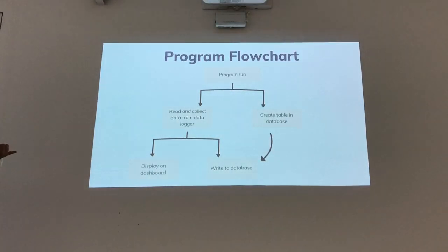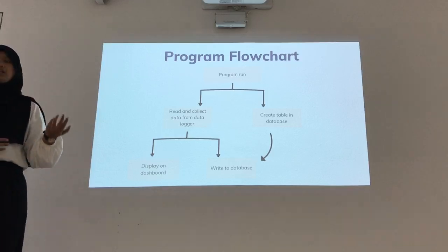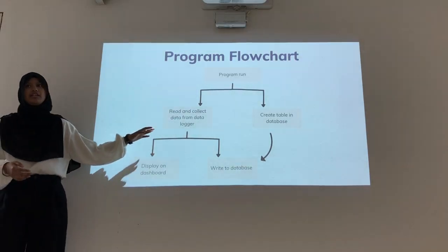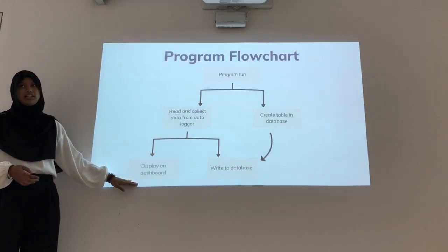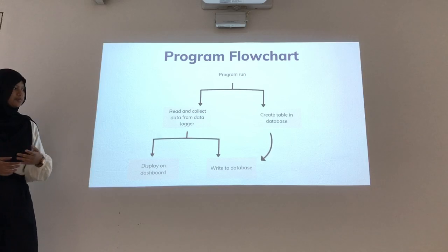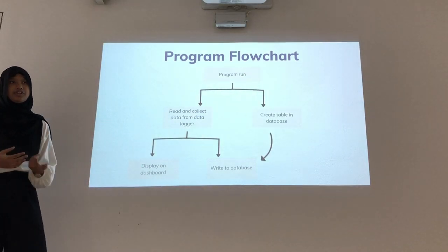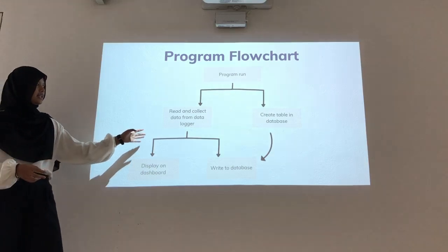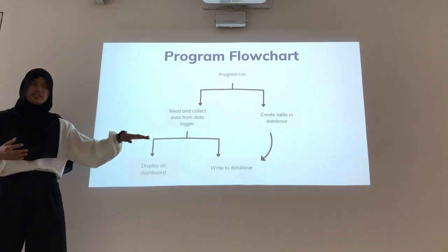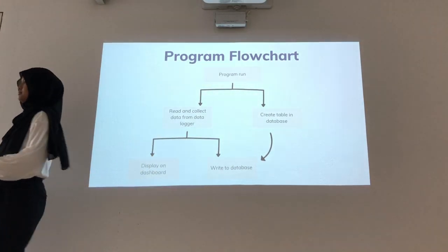So when the program runs, two different things will happen. On the data logger side, it will read and collect data and display it on the dashboard. It will scale accordingly as well. And on the database side, we will create a table if there is not already an existing table, and it will collect the data from the data logger after it is scaled and write it into the database.